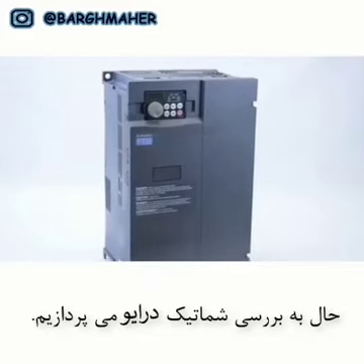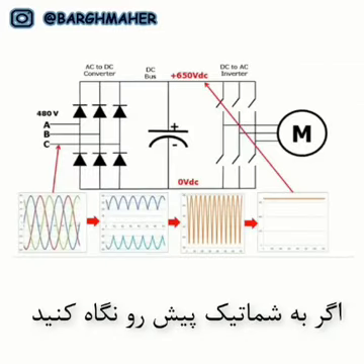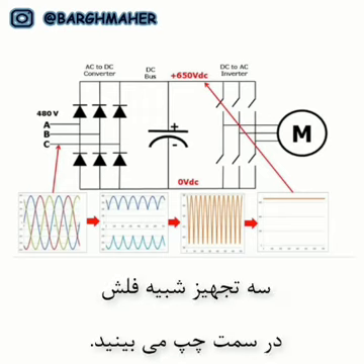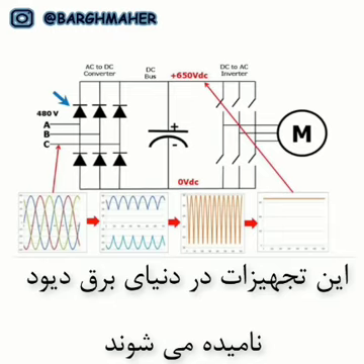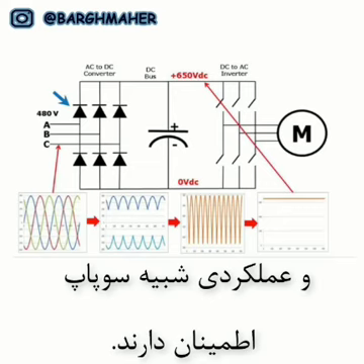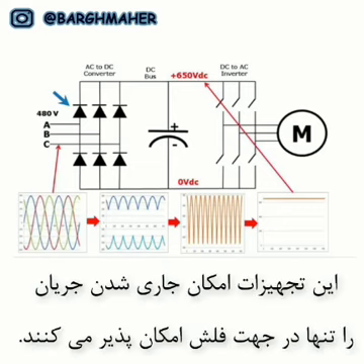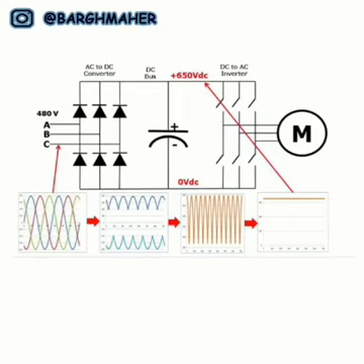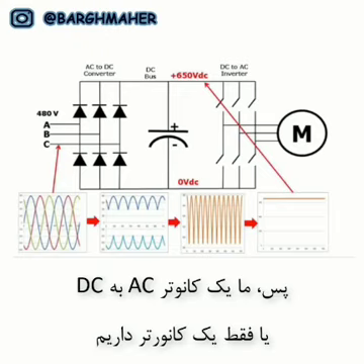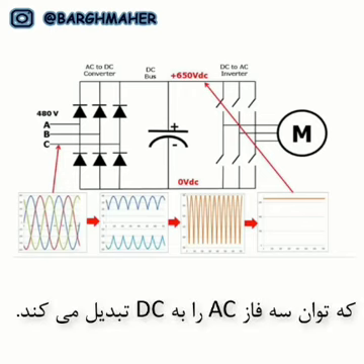Now, I'd like to look at a schematic of a VFD. If you look at the schematic in front of you, you will see three arrow-looking devices on the left. These arrow-looking devices in the electrical world are called diodes. In the mechanical world, in the plumbing world, we might think of these as check valves. They basically let current flow in only one direction, that is, the direction of the arrows. So we have an AC to DC converter, or just converter for short. This converts the three-phase AC power to DC.